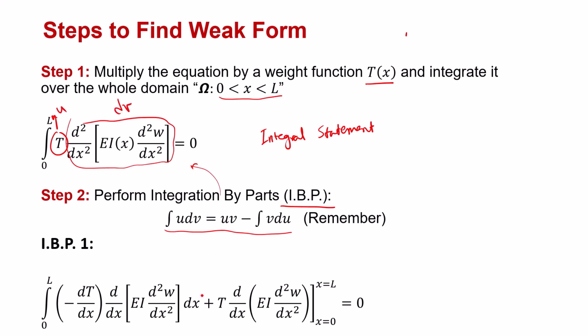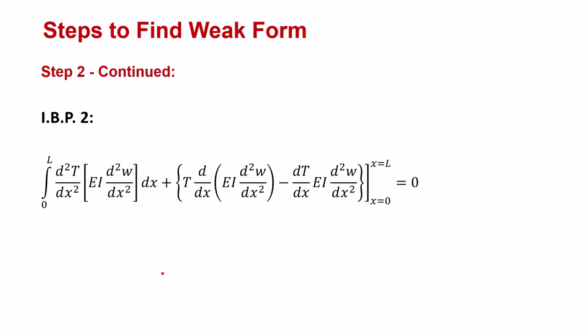After the first integration by parts, we reduce the derivative order acting on w by 1. Now something very important appears, a boundary term. This boundary term is this one, as you can see here. If you notice carefully, this expression involves the shear force, and this is not a coincidence. Natural boundary conditions start appearing automatically through these boundary terms. But we still have a third order derivative inside the integral, so d here and d squared here. So we integrate by parts again.